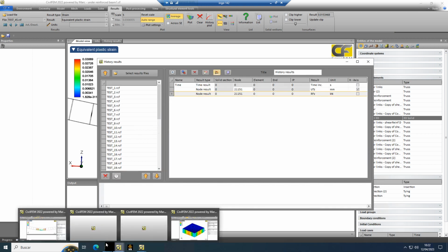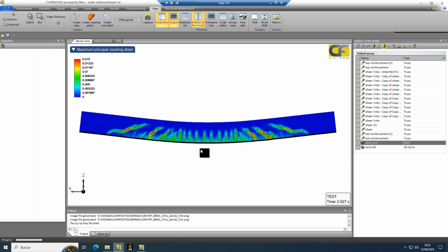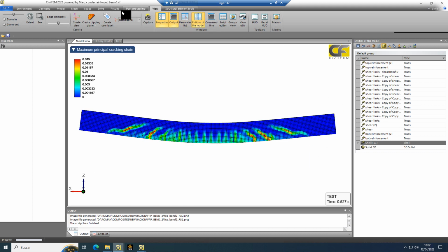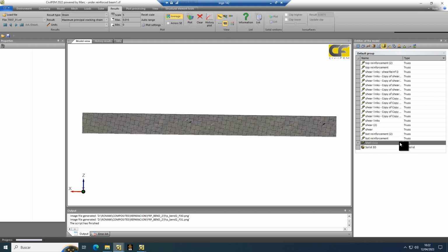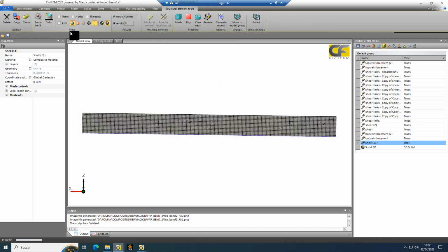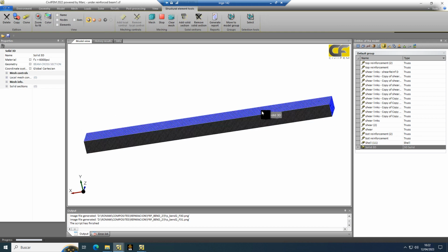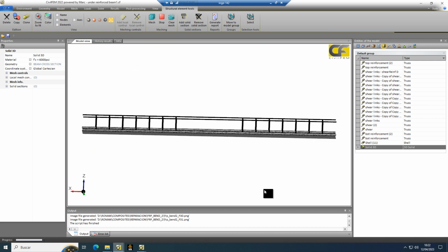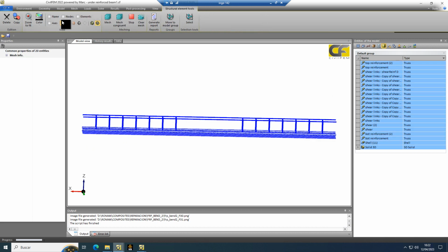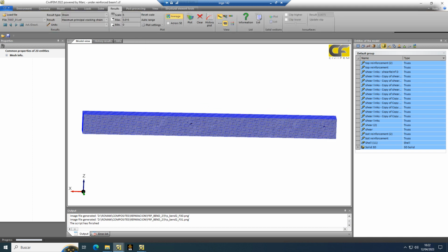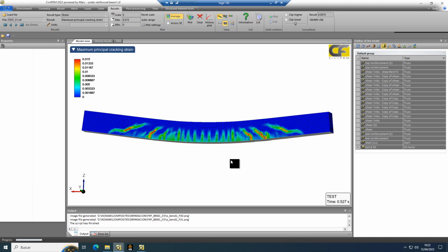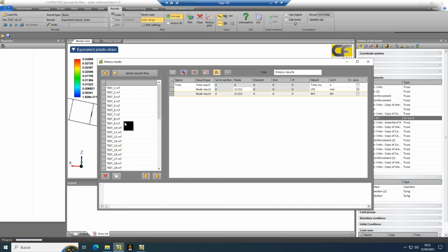So well, in the next model, what we have done is adding this reinforcing, and the reinforcing is this shell element that is added on the bottom for the bending reinforcing. The result we have seen is that now the failure is due to shear. Now we have these shear cracks. Now bending cracks are reduced a lot compared with this other model.